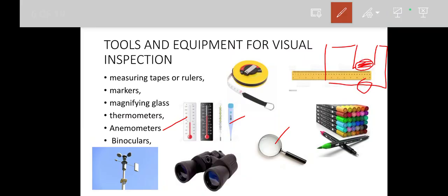Okay, if you provide an opening, all the winds will enter through this and try to exit out. So on this surface we can see a lot of spalling and corrosion might have happened when compared to other faces. Why? Because the wind has taken the direction to enter this narrow path and then come out.